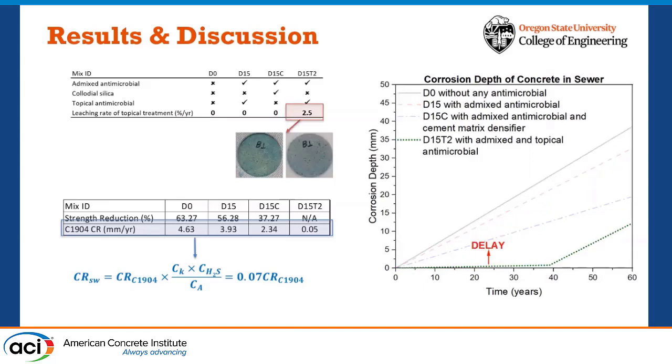And as I mentioned, we had almost zero corrosion rate for the topical one, but we defined a delay factor here, because the topical on the surface might be leaching. So after a point, our admixture might be losing its effects. So the delay factor is something that we are still working on.